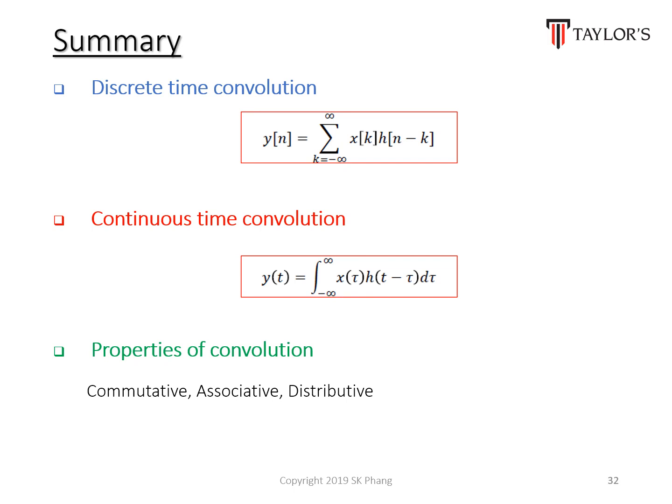And then we move on to continuous time convolutions, where you cannot use method 3 anymore, but you can still use methods 1 and 2. But for the graphical method, you can only use it if both the graphs are square waves. Then only you can find out the area, and area multiplied by the magnitude. And lastly, we learn about properties of convolutions. There are 3 of them, which are the commutative property, the associative property, and the distributive property.